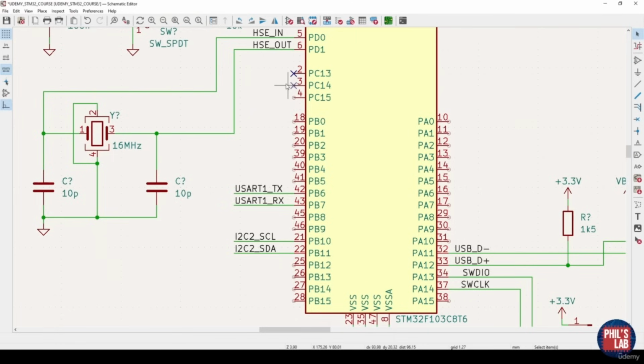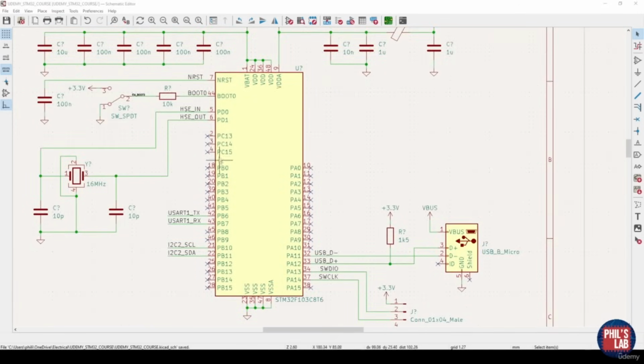and then I can also press Insert on my keyboard, and this will add the same command I just used, for example, this no connect flag, to the pins below. And I can just fill in all of these pins with no connect. So let me just do that. And here we go. Now all of the unused pins have these no connect flags, and this is good practice to make sure you don't have that many ERC, or electrical rules check, warnings.